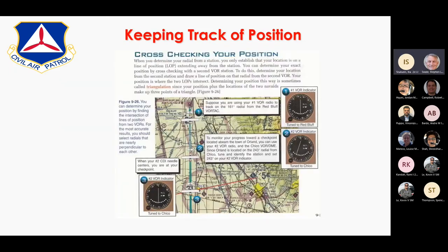So ultimately, all the things that we've mentioned so far, I'm going to ignore ADF, of course, unless you're listening to KGO. The VOR and a sectional are really important tools to help identify where you are. We'll get to GPS later. The important concept is that you cross-check between the two of them. Where does the VOR say that I am? And you interpret the VOR. Then you take a look at the sectional. Then you look out the window and apply pilotage.